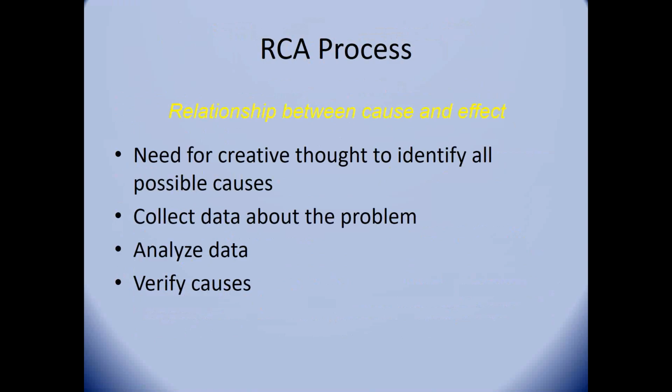You know, maybe what was the pressure at the time it happened? What was the temperature at the time this happened? What other factors may have been happening? Is there data in the CMMS system? Is there data that operators collected or wrote down that we can use in solving the problem? And then how are you going to analyze that data? Sometimes if it's a major problem, we need to take a little bit of time to analyze the data we have and make sure it's good data, make sure the data relates to the problem.